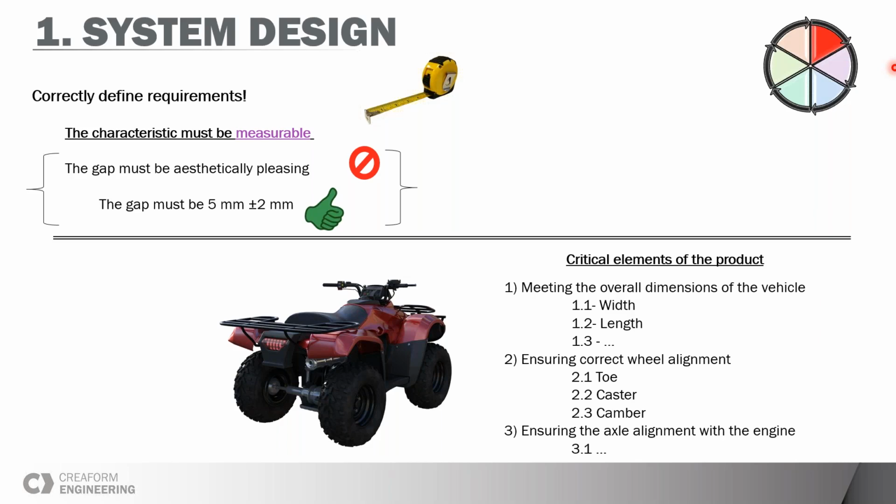What I mean is that if you want a statistical analysis on your tolerance stack-up, and all the parts, for example, are manufactured at the edge of their tolerance or outside of it, and then reworked up to the limit of the tolerance, that means all the parts you manufacture will be at the limit of the tolerance. So it won't follow a nice bell curve, a normal distribution. In that case, you cannot use the statistical analysis in the same way. So there's a lot of specifics.